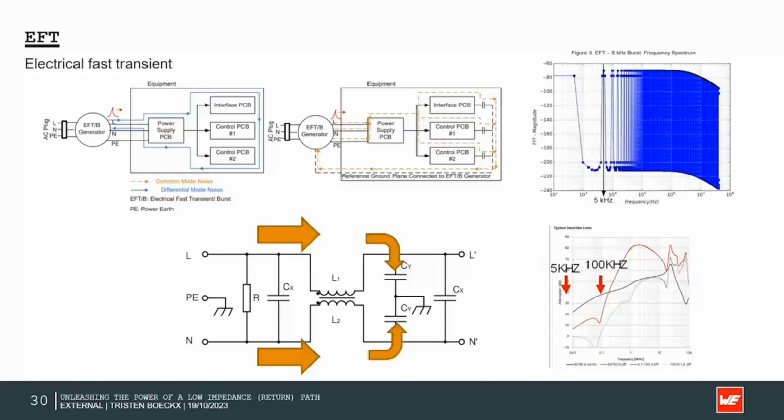A nice add-on could be to replace or to add a resistor where the resistance is. And a last small tip is that the leads need to be as short as possible to have less parasitic coupling to other parts of the system.